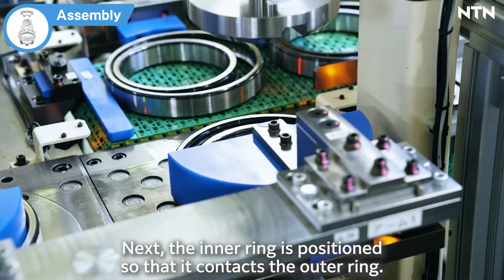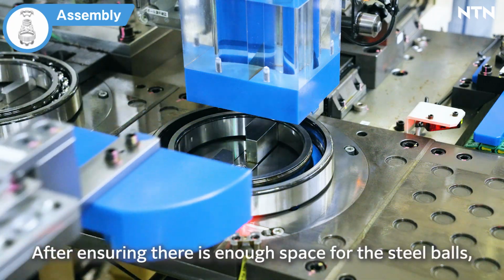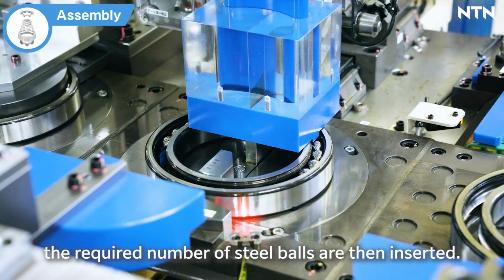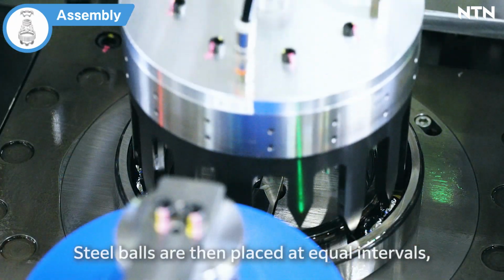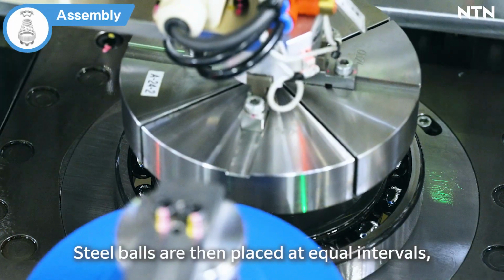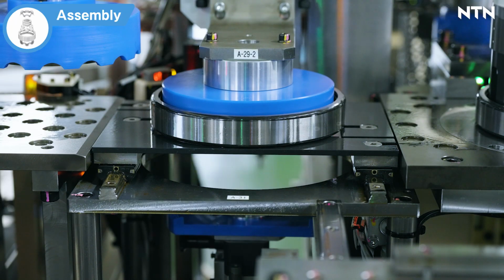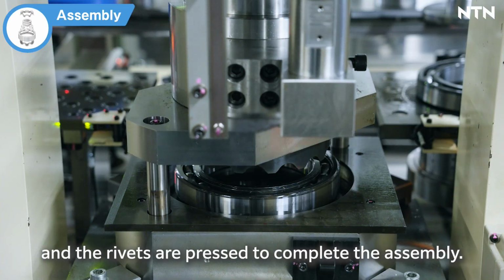Next, the inner ring is positioned so that it contacts the outer ring. After ensuring there is enough space for the steel balls, the required number of steel balls are then inserted. Steel balls are then placed at equal intervals. The cage is attached from the top and bottom, and the rivets are pressed to complete the assembly.